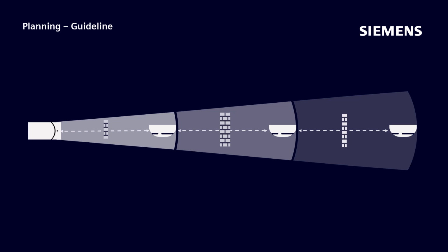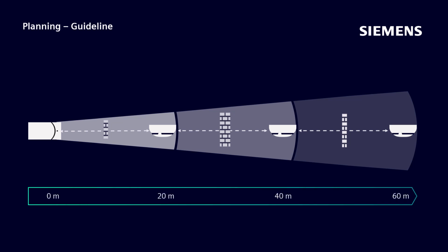However, in buildings with multiple walls, the transmission distance is reduced. When there is one standard wall made of materials like concrete between 2 wireless devices, the typical range drops to about 20 meters. In this case, using 3 hops, the total reach from the gateway to the farthest device is generally around 60 meters. It's important to follow the guideline of having no more than one standard wall between 2 wireless devices to ensure reliable communication.